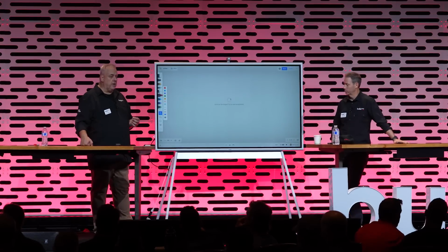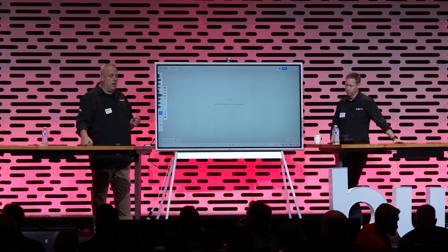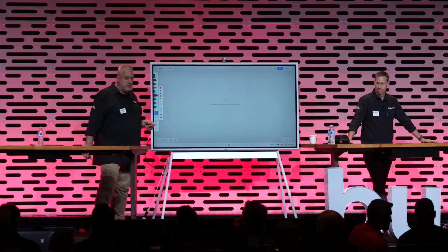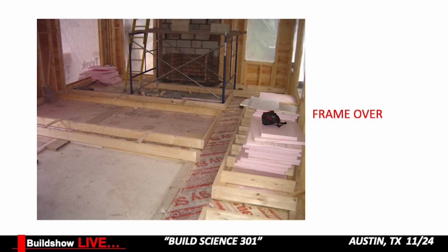One of the most important words in building science is continuity, right? So if I design the house properly and do that turn down slab detail, chances are I am doing a full coverage of pretty much the floor plan with insulation without any thermal break. It's literally a floating floor, right? So it works really, really well. Works really well. Let's look at some other options, right?